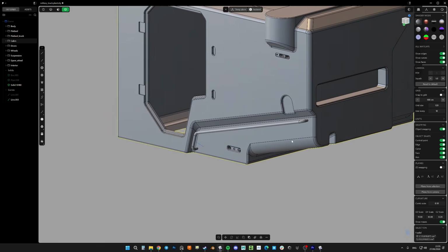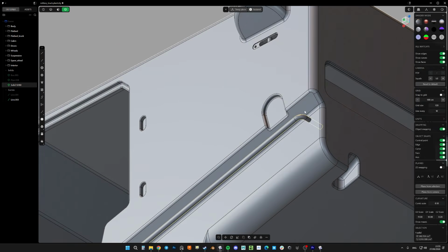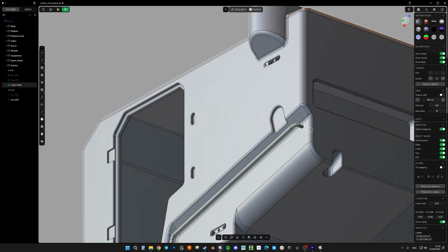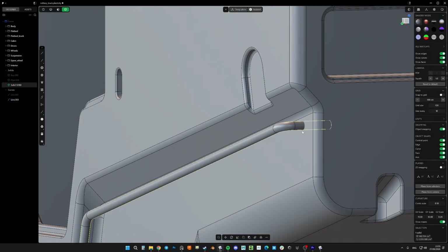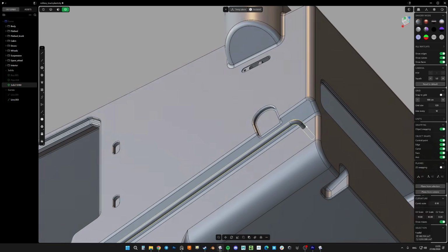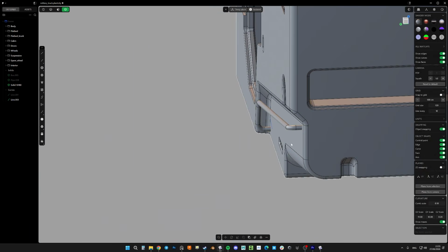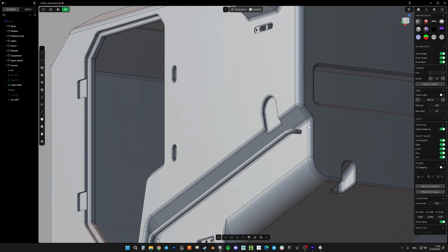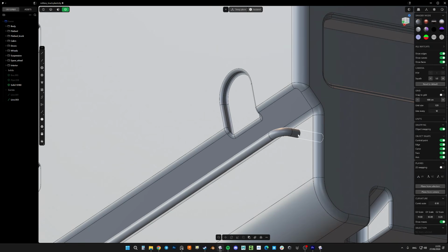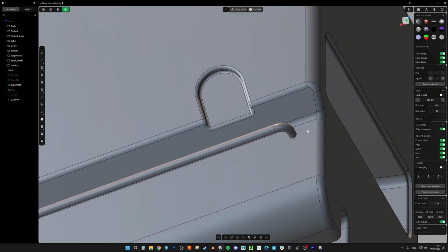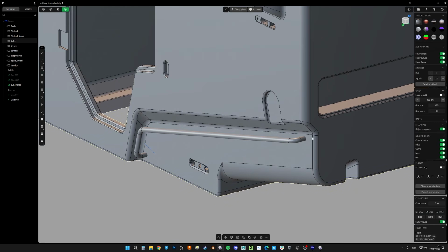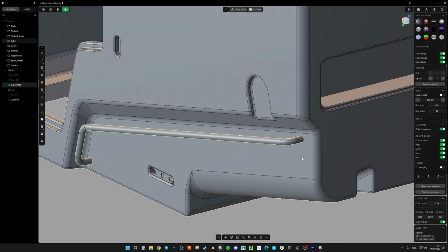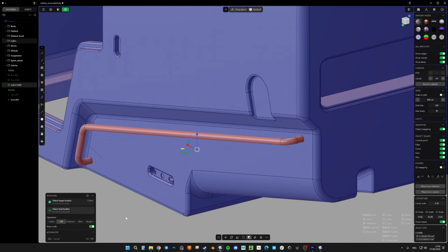Also, another piece of advice: when you create a pipe or some railing that goes into the body, don't leave it as it is, just one mesh piercing another. It looks very unappealing, not realistic, and there are many ways to solve it. For example, creating a hole in the main body. We can select our body mesh, then the pipe, and apply boolean with the keep tool slider activated.